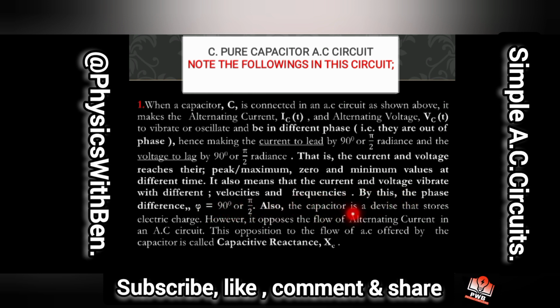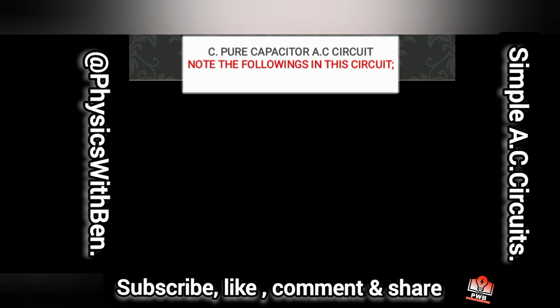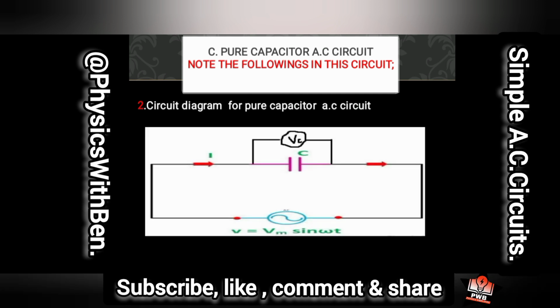Also, the capacitor is a device that stores electric charge. But for this type of circuit, the capacitor also opposes the flow of alternating current, and this opposition to the flow of alternating current offered by a capacitor is called the capacitive reactance. This is a summarized knowledge, what you need to know about a pure capacitor AC circuit, summarized here for you. Next up, they may ask you to draw the circuit, which I drew before. This is it here.